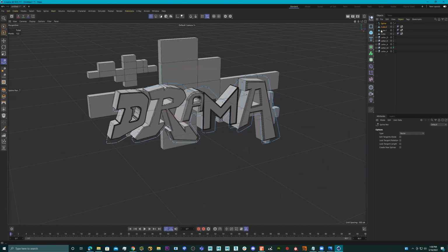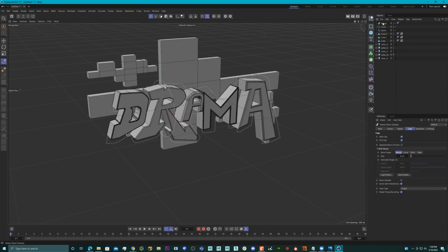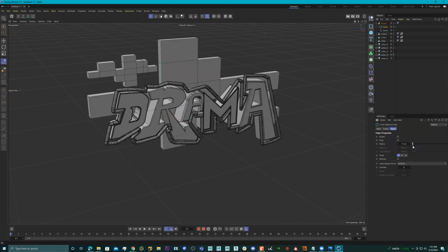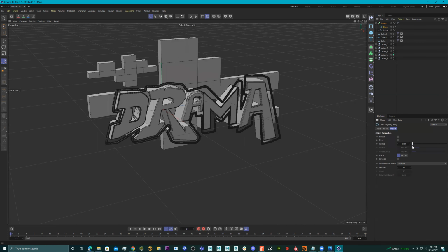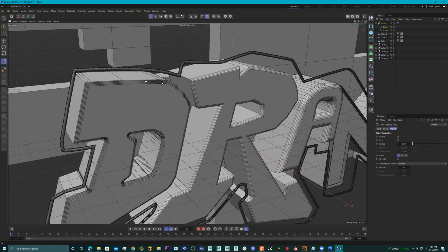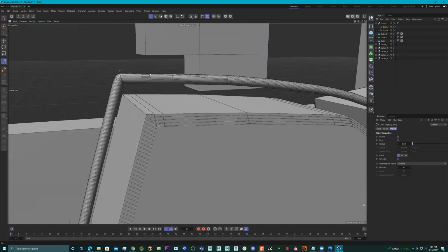All right, so we have this right here. We'll go ahead and get ourselves a circle. Drag our, oh no, we need to get ourselves a sweep. And the way sweep works is you have your spline on the bottom and then you have your circle right before the spline. And then the radius of the circle will be the radius of this.